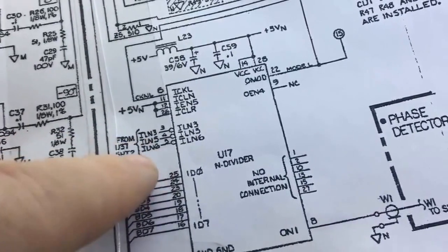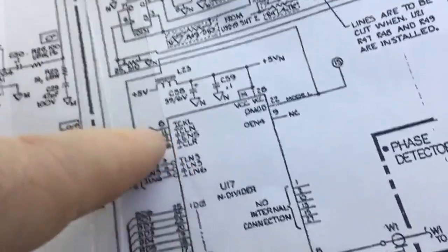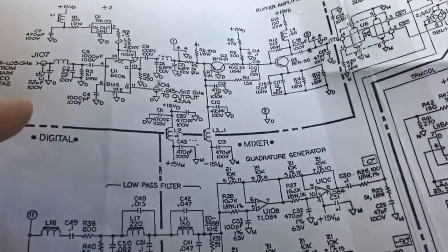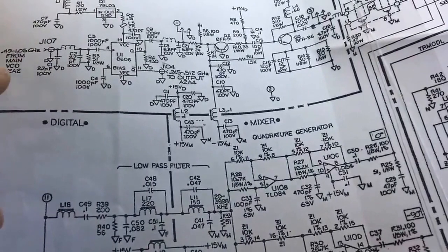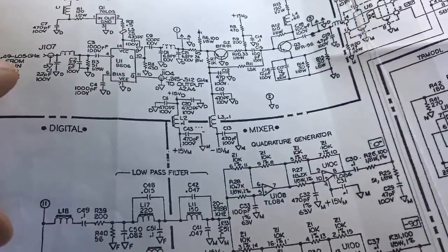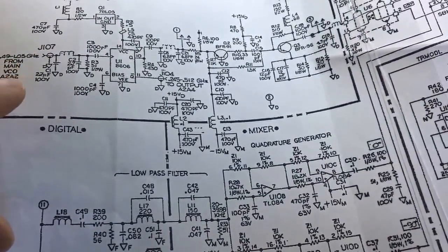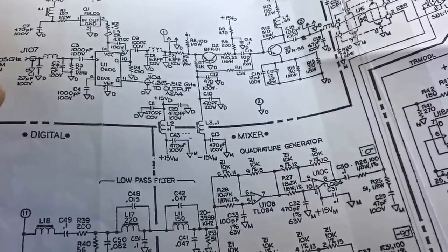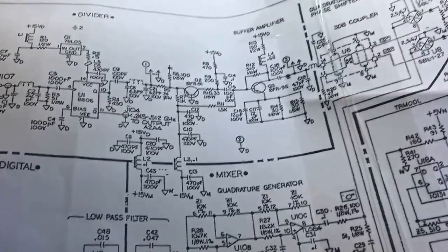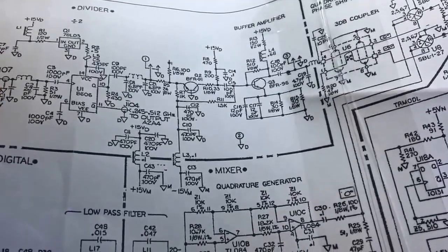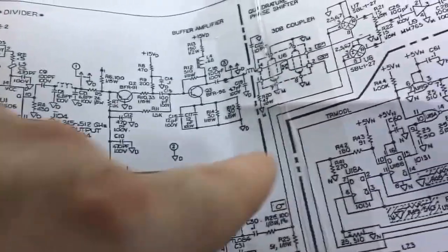But anyway, I've got these inputs here which I haven't even looked at yet. I don't know what they are. I haven't traced those yet. But I thought I'll just look at what I know. This is the 800 megahertz. Well, sorry, the high band VCO. So that's the 0.49 gigahertz to 1.05 gigahertz from the main VCO, right? Which I know is the one which is noisy and jittery when it's got that fault, and it steps by that 20 megahertz amount. So I know this is coming in wrong.